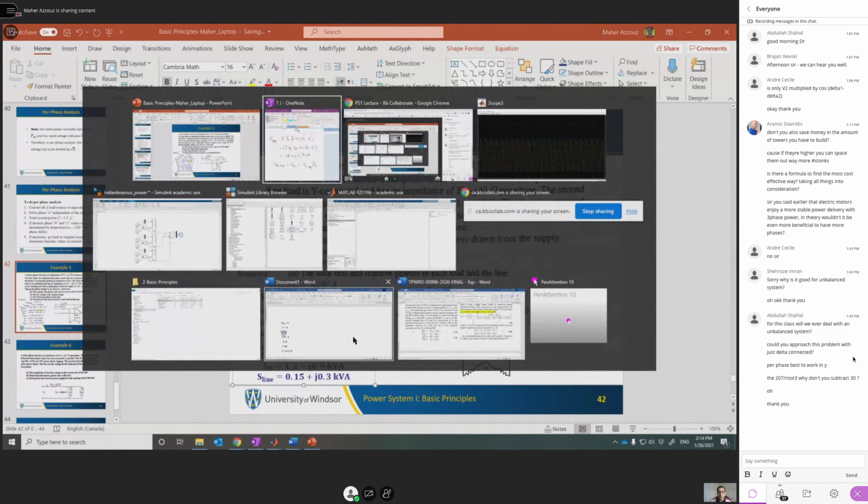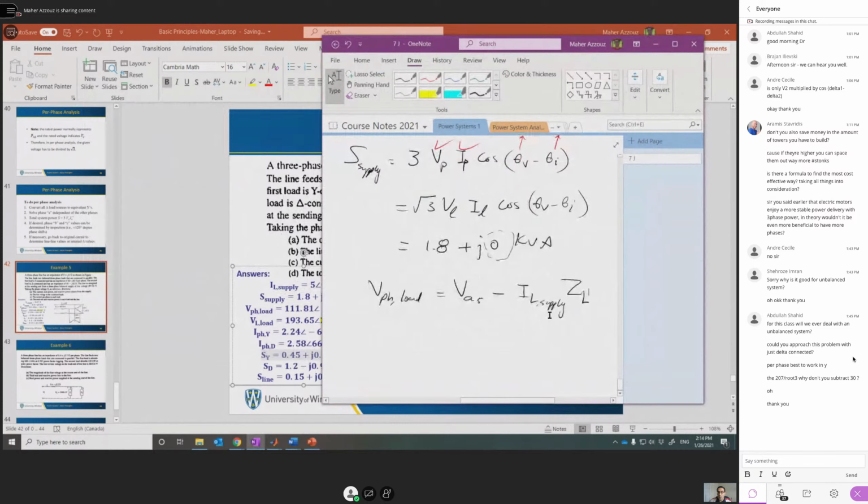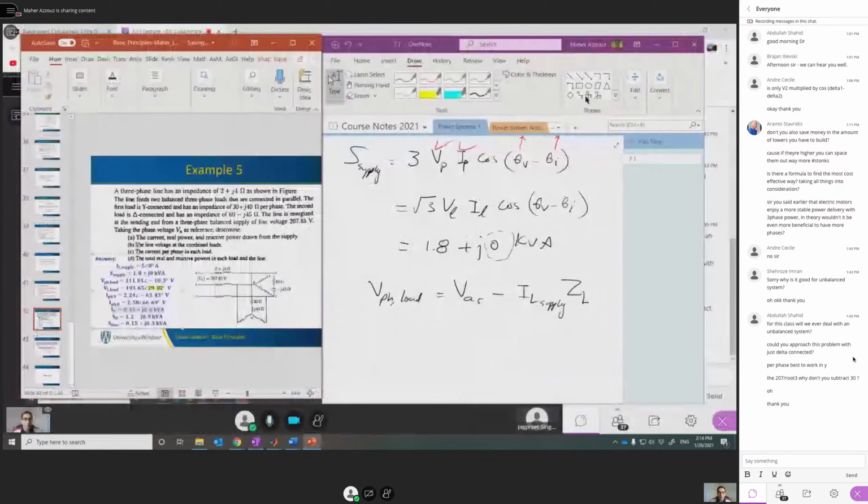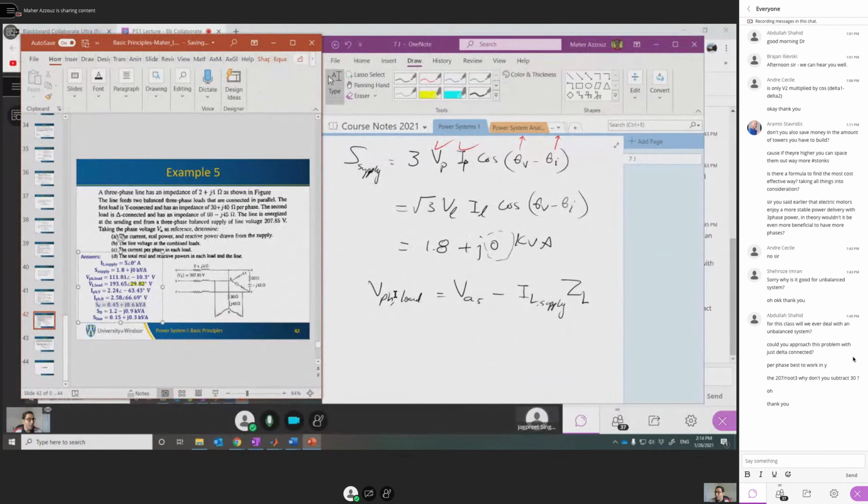Okay, now, so I'm explaining the procedure. Let me minimize this. So you get the phase voltage, and this phase voltage, as we know, is like this. So this is VA. VAB should be leading by 30 degrees. So for V line load, you should multiply the magnitude by √3 and add a phase shift of 30 degrees. Okay.